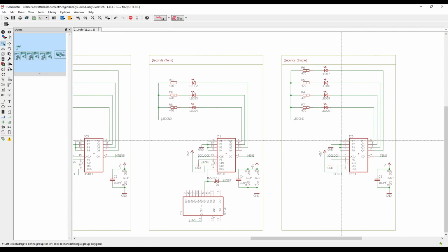Anyway, it goes into seconds, so it should go into the clock signal. And then the output of this, so once it gets to 9, the clock out goes to tens. Tens goes into clock in here, and the IC clock is still the clock signal, so it ticks over at the same clock signal. And then this is the out here.